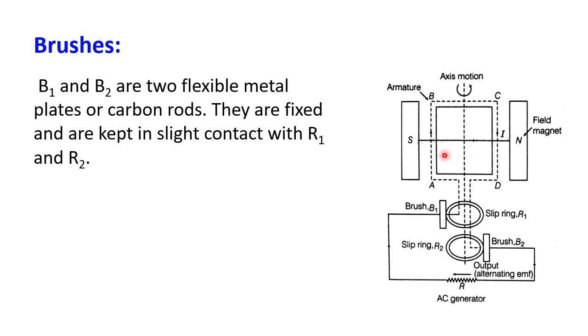So the direction of current is changing, which is nothing but the polarity continuously changing. As the direction changes, we can treat that as polarity, so there are positive and negative peaks continuously. As we are rotating with uniform angular velocity, fixed frequency alternating current will be generated across the resistor. That output will be alternating EMF or alternating current.